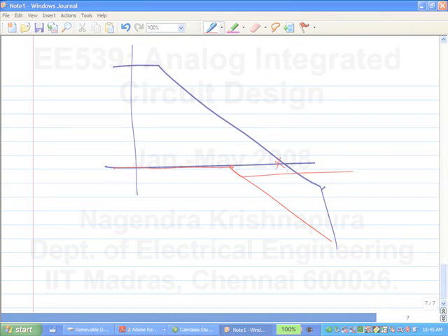The question was about the common mode capacitance used in the common mode detector. Now, let's say the rest of the amplifier has this magnitude response. Now, if you cascade it with a low pass filter whose corner frequency is set by RCM times the input capacitance of the common mode detector, then you will get a response of this sort, which is unstable.